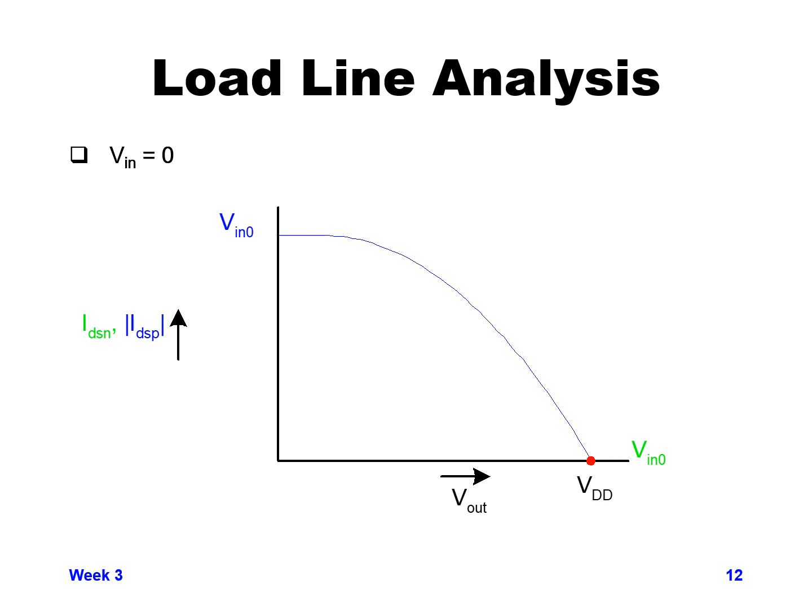Keep in mind, though, that our Vn 0 curve for the NMOS device, which is the green curve, is NMOS when the gate to source voltage is 0. NMOS device is cut off, has 0 current. It's just a flat line at 0. That's why you don't see the green curve there. But where those two curves intersect is basically where the current value is equal to 0. And so that's why the red dot there is where Vout has to equal VDD, and we have 0 current.